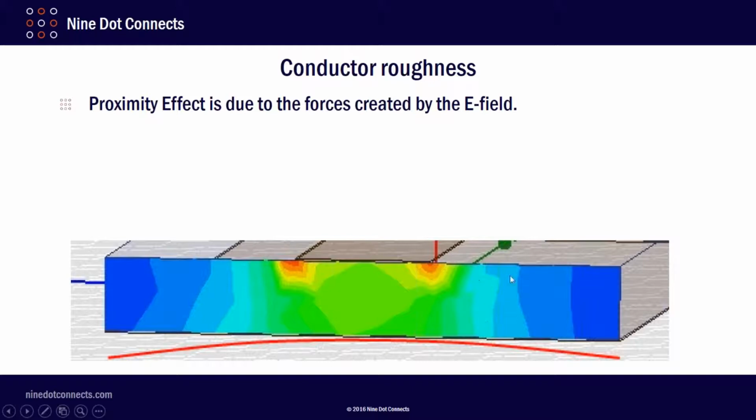The thinner this dielectric is, the closer the positive and negative charges are, therefore the E field is going to be stronger. That attraction between the positive and negative is going to be greater. So whatever electrons were in the top of the copper will be pulled down even more toward the bottom of the copper. So that was why the answer D was correct.